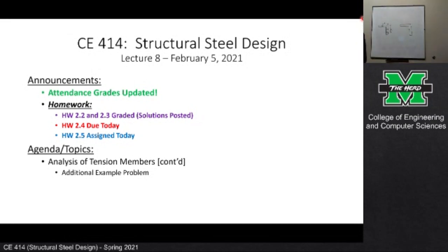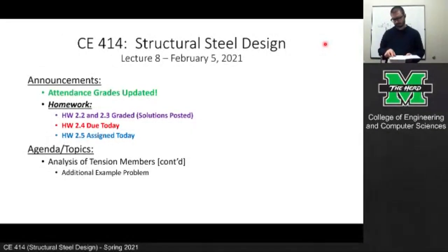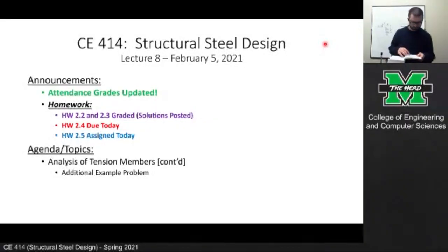Now, there was another hand raised. I think that was Mr. Adkins. Did you have a question? I was looking in the steel manual here. It was related to the 80 KSI part of the tensile stress. Yeah, I'm going to pull my steel manual up right here. Go ahead. According to the manual, for wide flange shapes with flange thickness over 3 inches, only the minimum of 58 KSI applies. Mm-hmm. So, in this case of the tensile stress, we should stick with 58 no matter what.